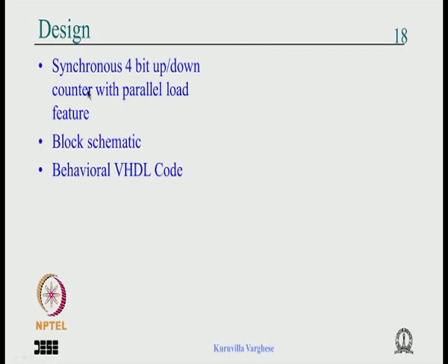So I want to design a synchronous 4-bit up down counter with the parallel load feature. That means it is a synchronous 4-bit counter. It should count up when the direction is 1, down when the direction is 0, and there is a load signal and a 4-bit input. When the load is 1, it should load the counter with the input value, and when the load goes low, depending on the direction it should go up or down.